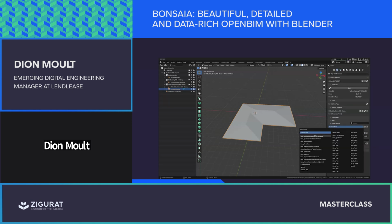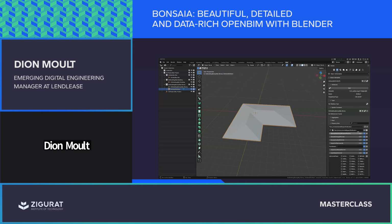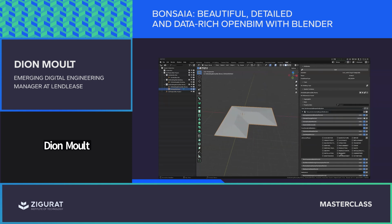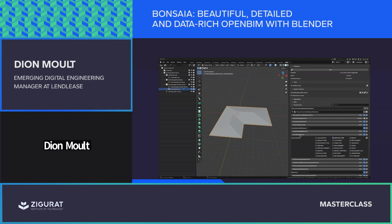And you would store, you can see here there's two here. This is the first one you do, this environmental impact indicator. This is the per unit, unitized one. This is the typical one. So whatever it is, climate change per unit. And you can see the life cycle phase. Typically, this would just be the manufacture of it, just the material data. And then from that, you would also specify the functional unit reference. So you would specify, is this per unit weight? Is this per unit volume, et cetera.